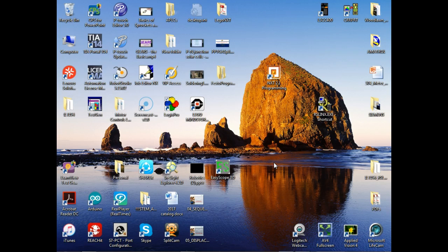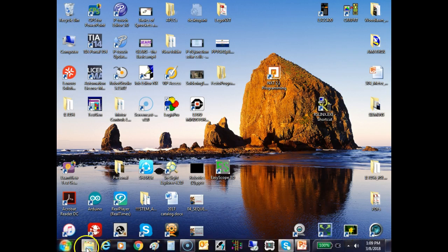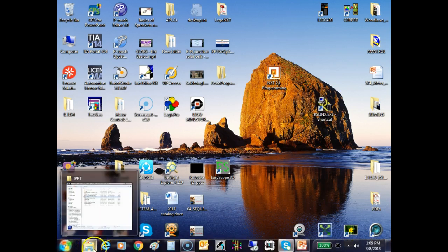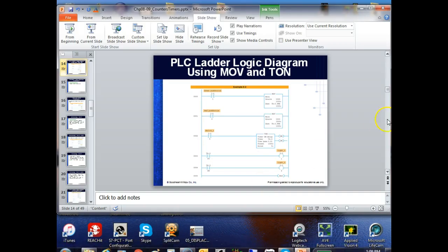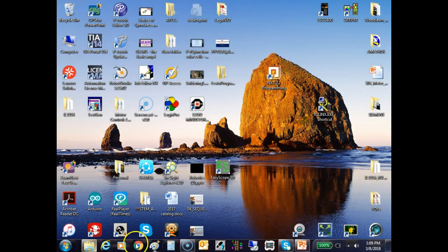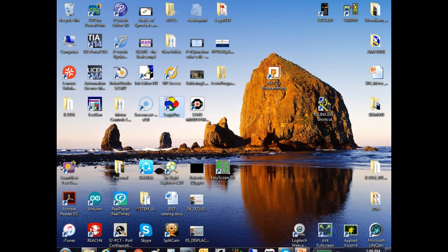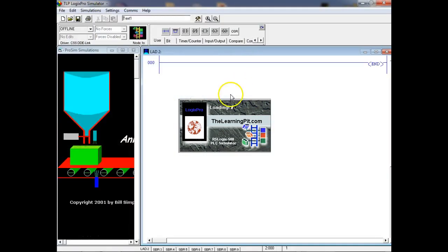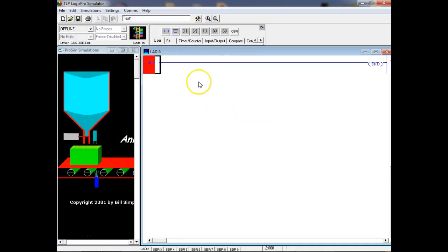By the way, another thing that we're going to do is that this guy talks about a master start-stop switch. How many master start-stop switches do you think you're going to run into? None. Probably none. What they do in industry is we use what we call a start-stop circuit. And I've showed y'all that several times in this lab. Some people call it a memory circuit, some people call it a seal-in circuit, some people call it a 3-wire circuit.